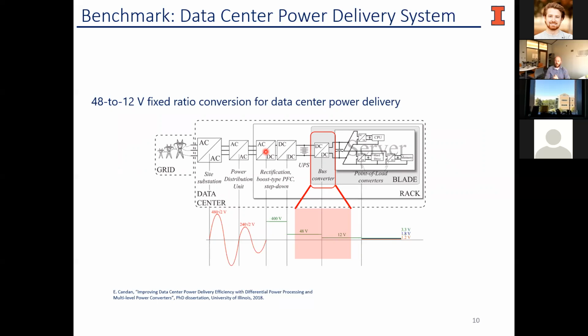They're all looking at doing this 48 to 12 volt conversion. They're all looking at similar power levels. And in general, while they don't print it, they're trying to get to very similar ripple specs and everything else along those lines. Although again, not every publication has done a great job of saying what the ripple spec is that they're designing for.